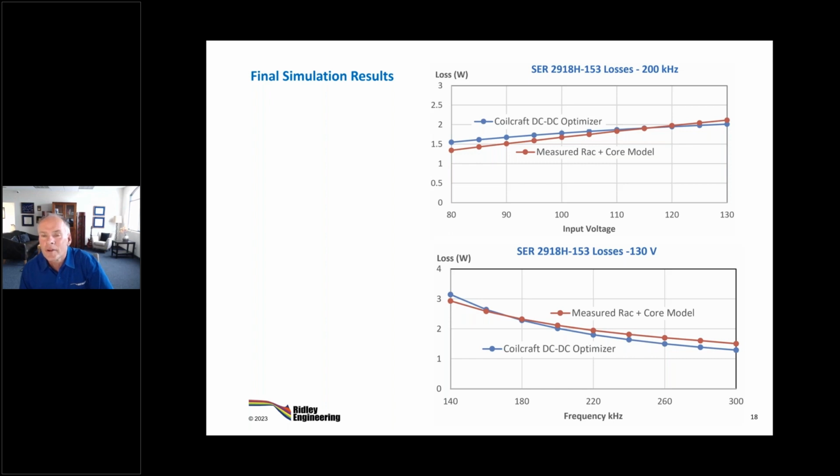Also, unless you count them, which we can do here on this inductor, nothing in the data sheet tells you the number of turns or the core area. So for all the other aspects of worst case analysis, like am I getting above 0.3 Tesla, which is a no-no for many companies, you can't even assess it. Again, a modern trend these days is for the people who make off-the-shelf magnetics to not want to tell you how many turns they've got. So hopefully they'll change that. If you push, they'll tell you. If they won't tell you, you just take them apart and count them. It can be a little difficult when you've got 140 turns, but you can get that done.